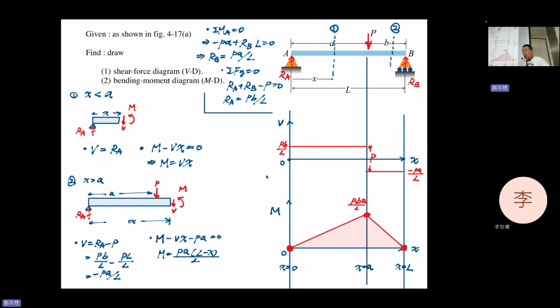All right. But if you see a free end, like this is a free end, you will have zero shear, of course, because there's nothing here. So please think about the support type and the result of your moment diagram and shear diagram. You can find out, oh, this is possible or not.